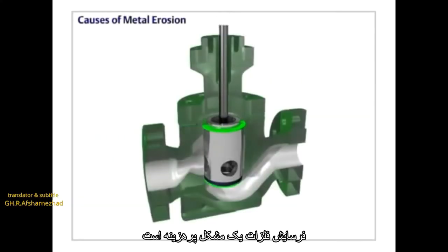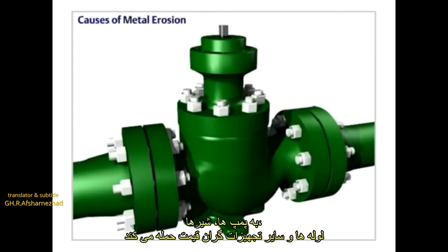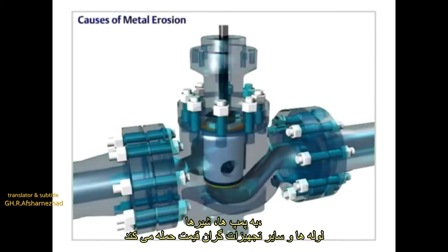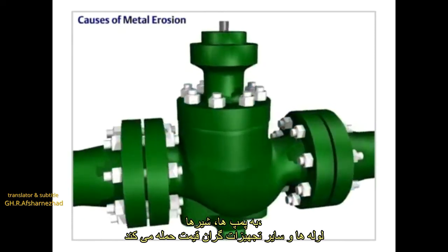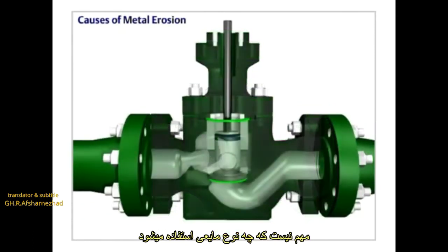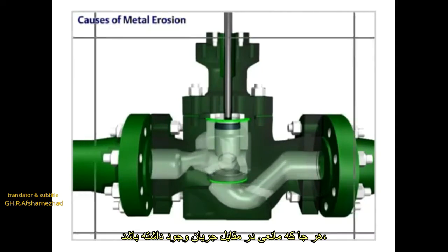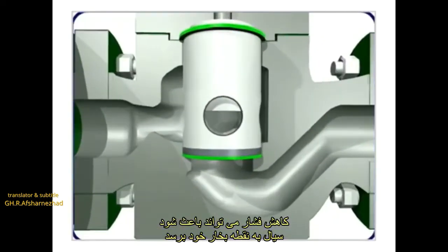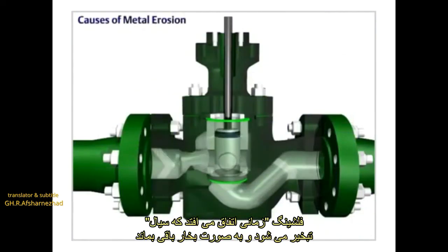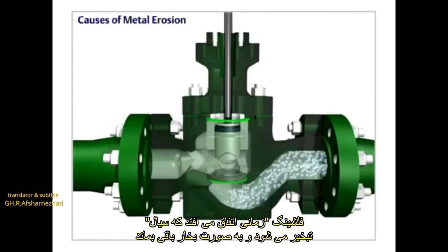Metal erosion is a costly problem. It attacks pumps, valves, piping, and other expensive equipment. No matter what type of liquid is being used, there's always the risk of damage from flashing and cavitation. Wherever there's a restriction in flow, the decrease in pressure can cause a fluid to reach its vapor point. Flashing occurs when the fluid vaporizes and remains a vapor.